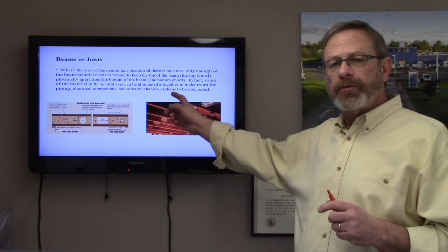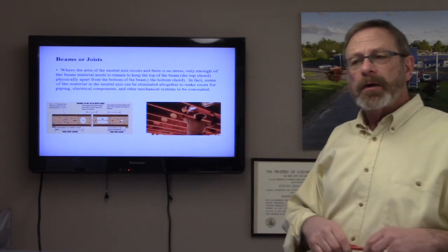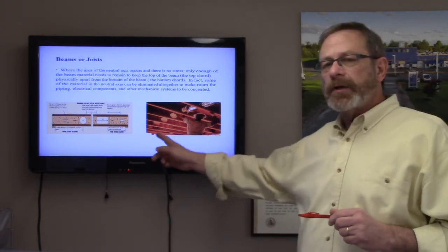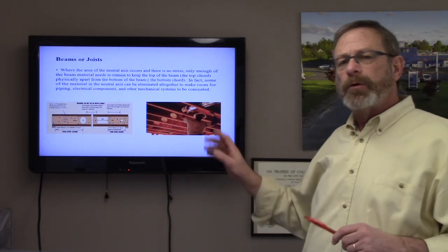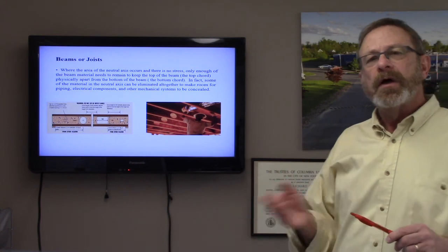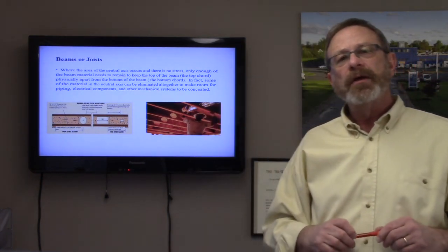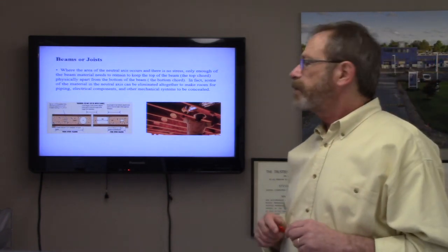We could always run between the cavity space along and parallel to existing joists or beams, but perpendicular, now we are able to run ductwork and wiring through a portion of those beams so that we don't have to create soffits or have things underneath the floor to under framing height, so nothing's interrupting our ceiling plane. That's a good thing for us as designers.